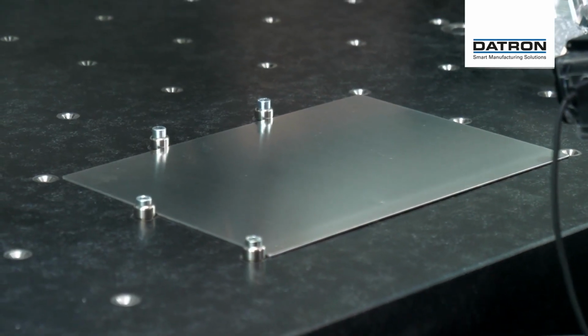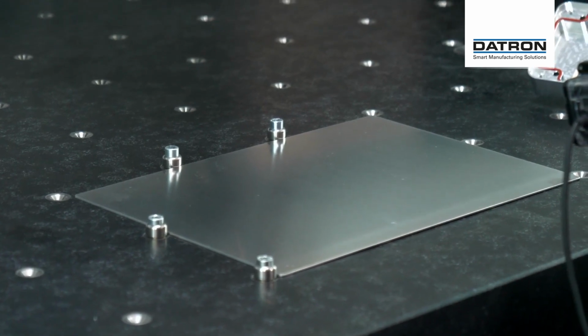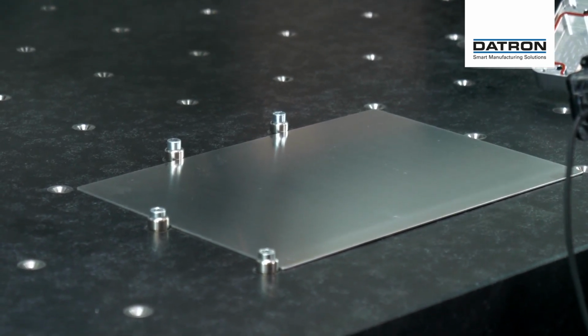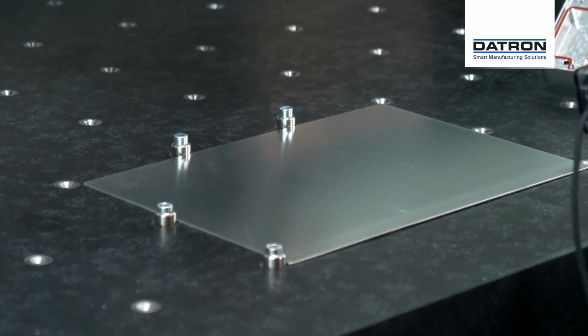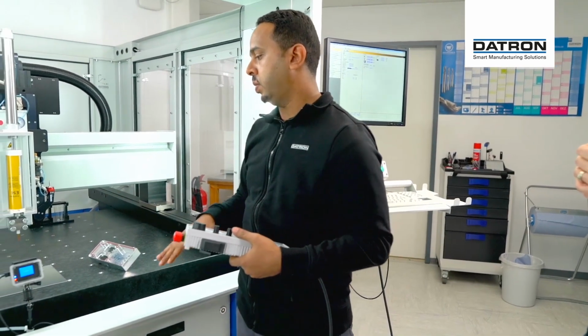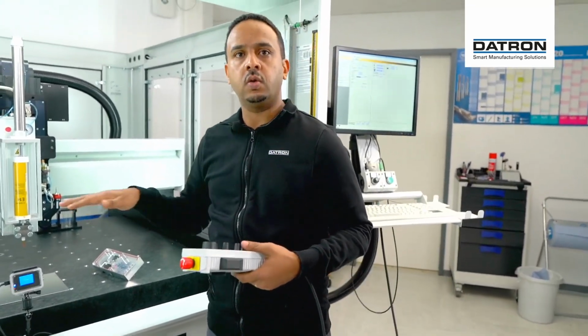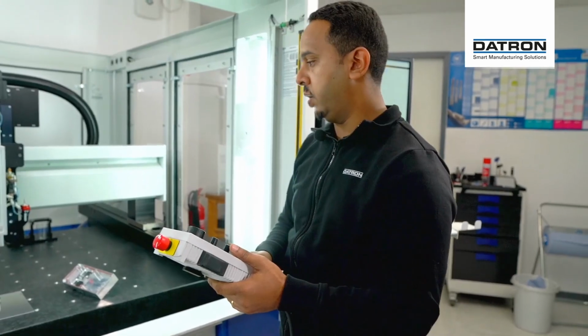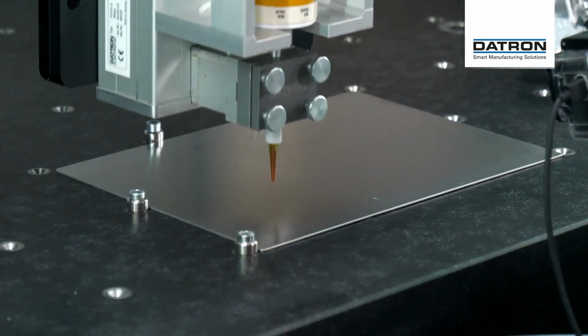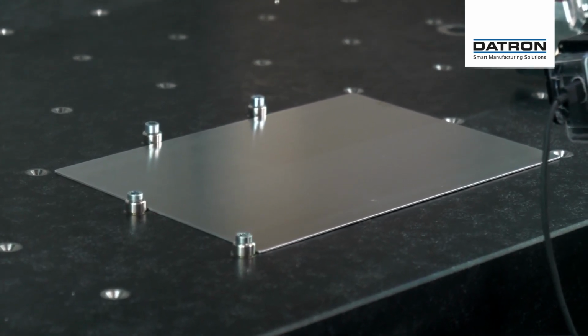Now the next aluminum plate is placed on the machine table. On the right side of our dispensing head, we have our mechanical probe. We are measuring the surface with the probe and correcting the height tolerance. Afterwards we dispense, or place the gasket, on it. We are moving to the first point and then start to measure the surface.